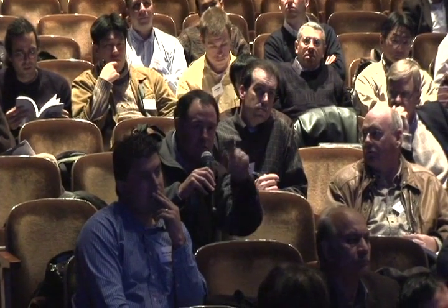I was looking at rocking structures, and I was just wondering what within the toolbox would be the best way to capture permanent settlement, vertical ratcheting down of the footing, not too dissimilar to the column with the plasticity theory.